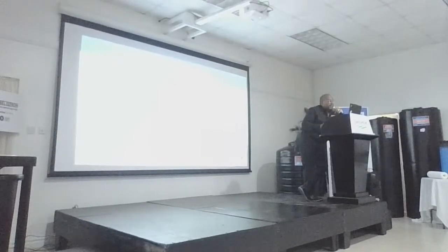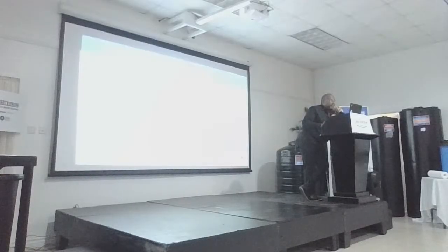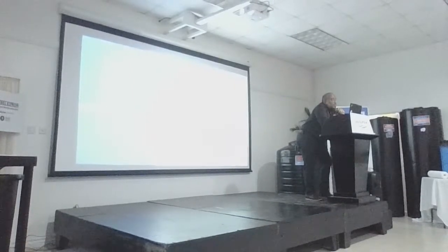So you'll see here that there's a soakaway where secondary treatment will begin. And these are usually a pit attached to your primary septic tank. What is a soakaway? A soakaway is a drainage system designed to purify and discharge the effluent below ground and into natural soil. So it will permeate into the walls, and the earth will help with the breakdown as well.